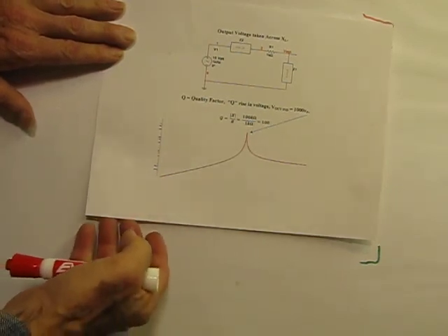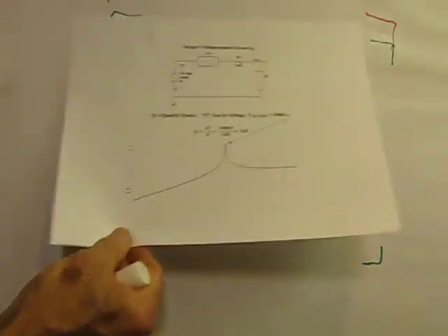Getting a Q of 100 is kind of hard, and realistically our input voltages are going to be a whole lot smaller than 10 volts peak, so we're not going to be seeing anything that's quite as fantastic. And the reason that the Q is lower is because inductors and their resistance typically limit that to some value quite underneath what we're talking about here.